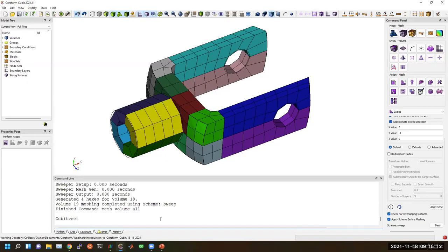So what we're going to do is set the U-Spline settings on all the volumes to be degree 2 with a max continuity of 1. Right now we support up to cubic U-Splines. You can try even higher order U-Splines if you want, but right now we only have test suites up through cubics. So you may be able to build U-Splines on higher orders, but you may encounter some inconsistencies with higher degrees.